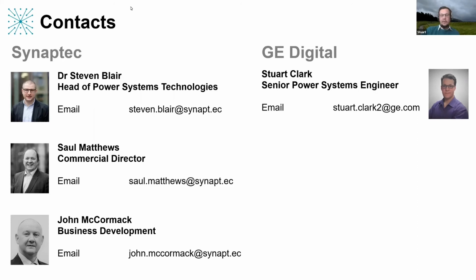That's fine. For control applications, you do want the data to arrive quickly, depending on your application. If you're talking about fast frequency response, like we had in the EFCC project, you definitely want your data to arrive within a certain window of time. And that's when things like making the choice of TCP over UDP for data transmission can be important. Setting your data windows carefully so that you wait as long as you're comfortable with for data to arrive, but not too long that it becomes useless for the control application.